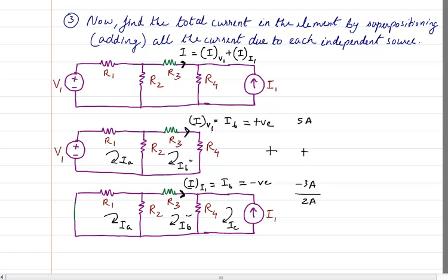So generally, if I have drawn a resistance like this, I will say that I have got a current of 5 amperes flowing through the resistance, and this minus I can represent by the opposite direction. So I will say that I have got a current going in the opposite direction, whose value is 3. So this is basically minus 3, and this is positive 5. When you add both of them up, since they are in opposite directions, you should not write it as 8. Don't write it as 8.